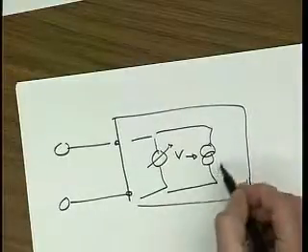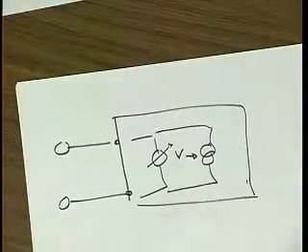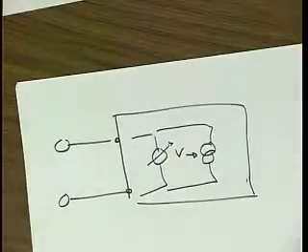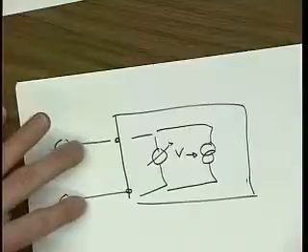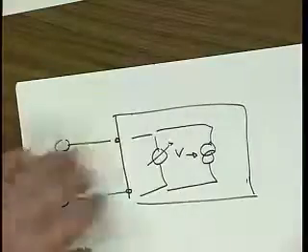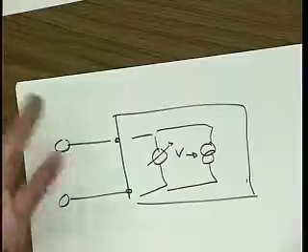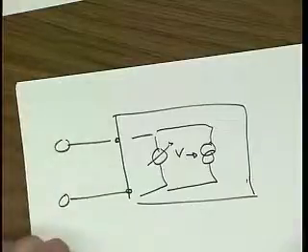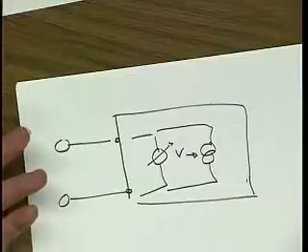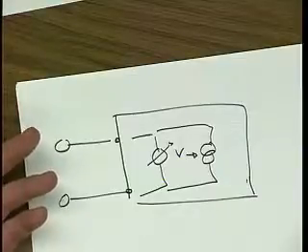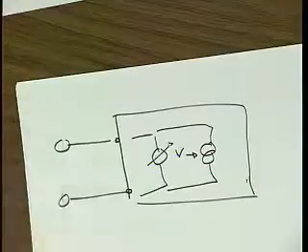Now, however you build this current source, you're going to get a certain amount of noise. In the end, that may be just the noise so that this appears like having 4 kTr noise, but it could be more. Most of the time it's going to be more. But if you're good at it, it can actually be less. So you could certainly make resistors that have less than 4 kTr noise, and maybe people would come and buy them from you.